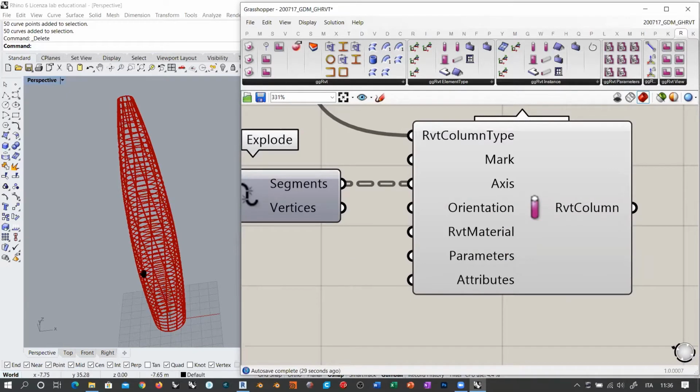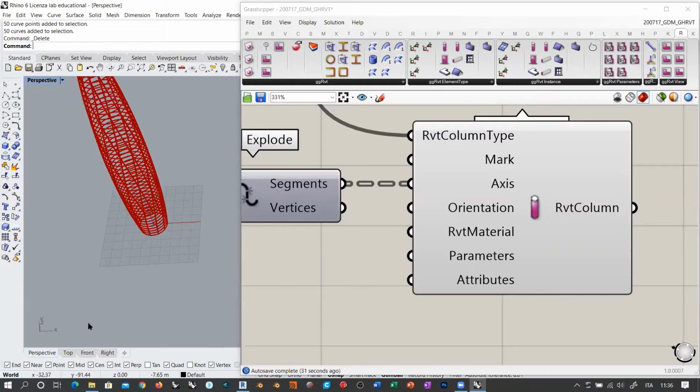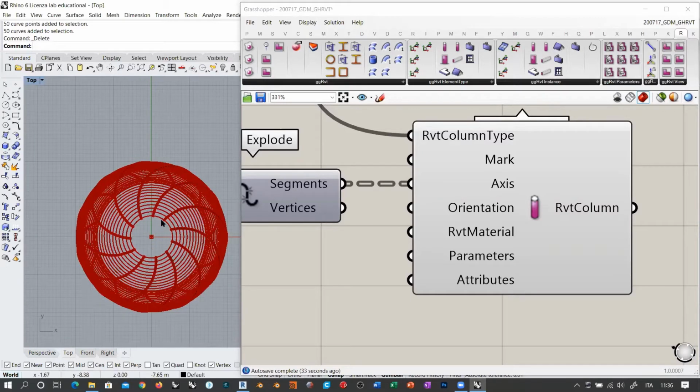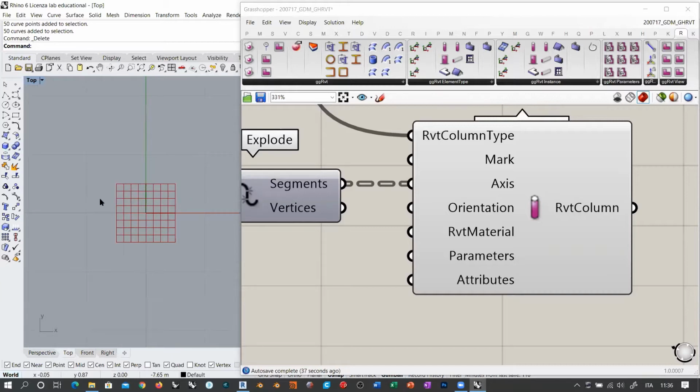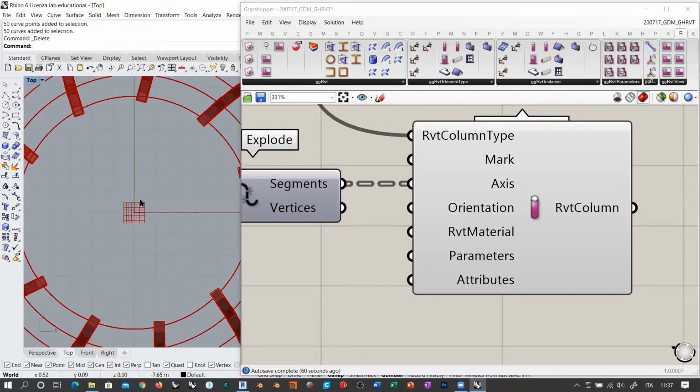Now, remember that when you customize a profile, it appears in the origin of the coordinate system, and this profile has already principal axes like X and Y, which are important, especially when you want to define beams. The beam orientation and the cross-section orientation affect the beam behavior, resistance and structural characteristics. So it's important to understand that profiles already have an orientation.